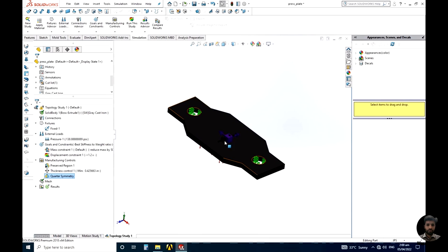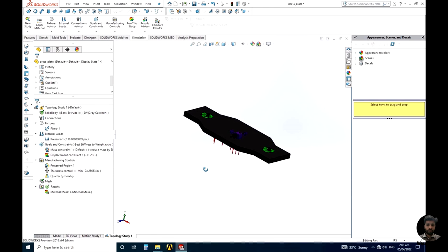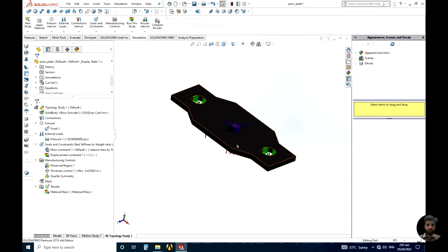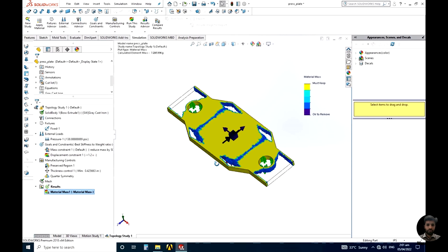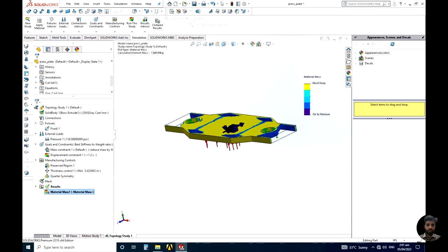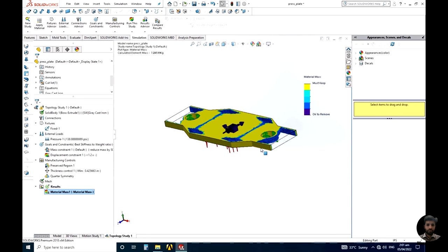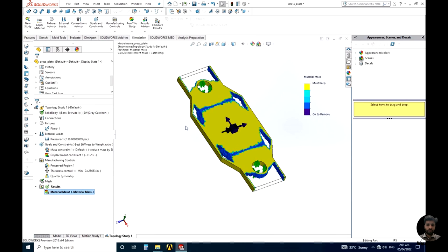Now the whole model has been defined, and now I have already simulated this model topology study, performed this topology study. So I only select the result and will show you how the Solidworks simulation remove material. Now as you can see, those faces that I want to preserve doesn't change so much. You can see the geometry of the part has been preserved on the outside,